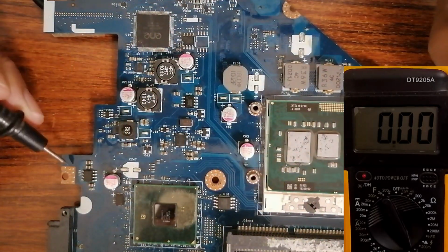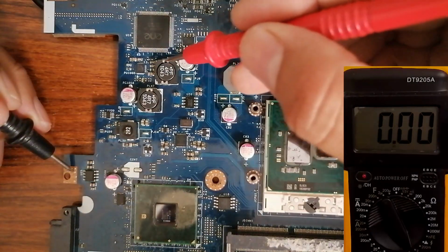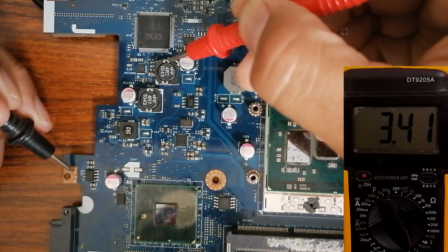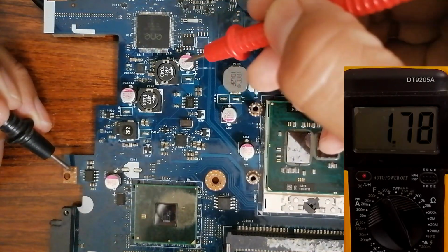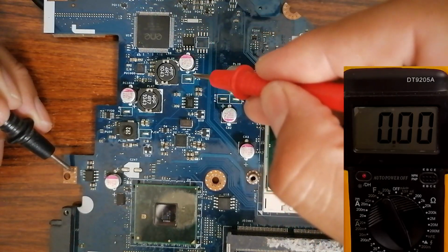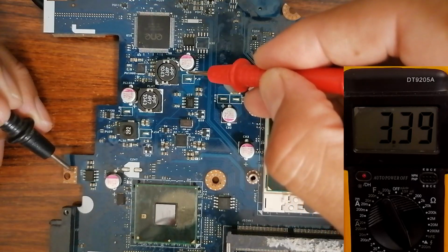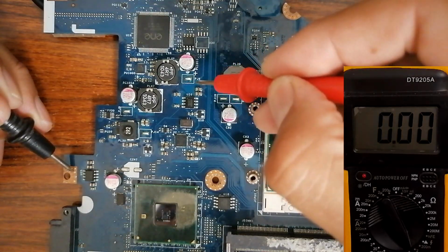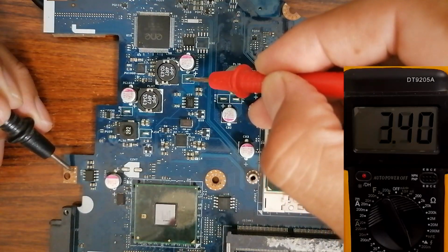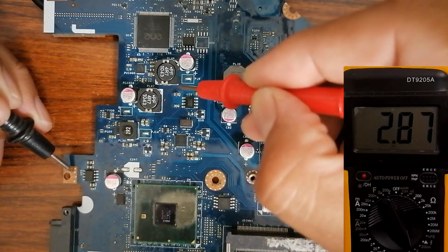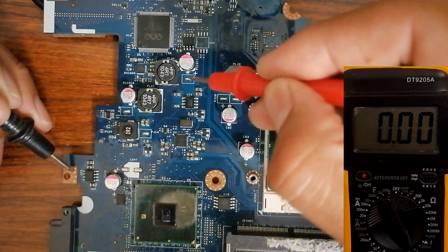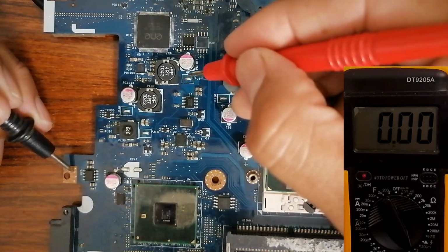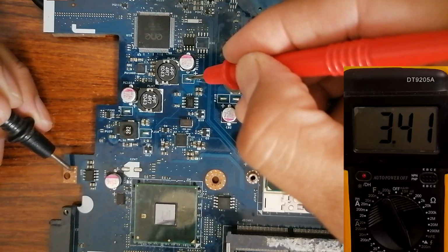So you can of course measure 3 volts for this circuit in the inductor here, as you can see, or in this capacitor, the plus terminal or positive terminal, or even in the pad. This is basically the pad or test point. So this is the first circuit. Here we have its test point. We have, as you can see, 3.3 volts.